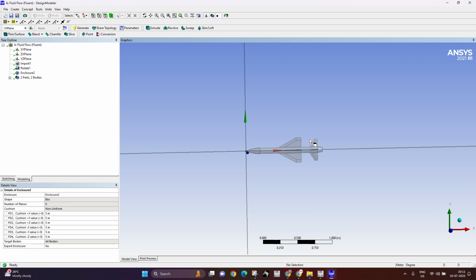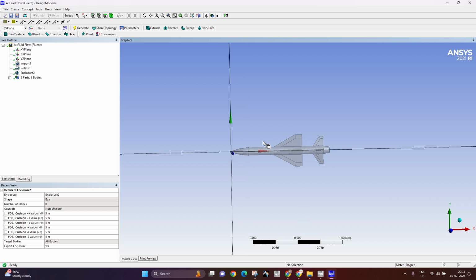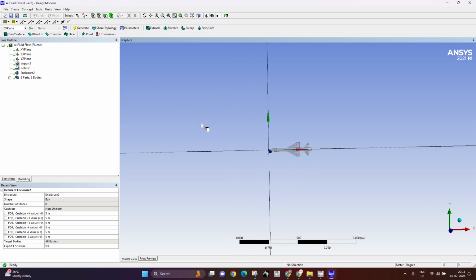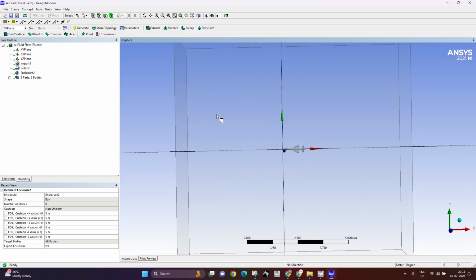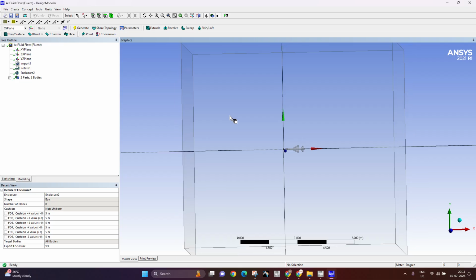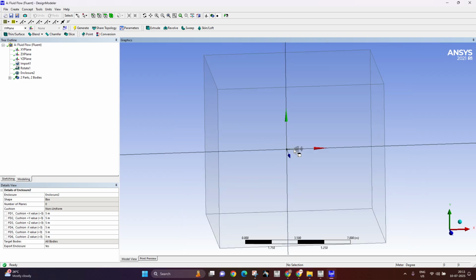If you treat your environment as a continuous medium, then you need to delete the object because let's take it simple, okay? In the real-time environment, the object will be solid and the air is cavity, na? Air is cavity. But now in the ANSYS software, it cannot comprehend real-time nature. So if it doesn't comprehend the real-time nature, it will make the opposite. The whole environment will be treated as a continuous medium, like a solid piece, and the object we need to delete so that it will be a cavity mold.